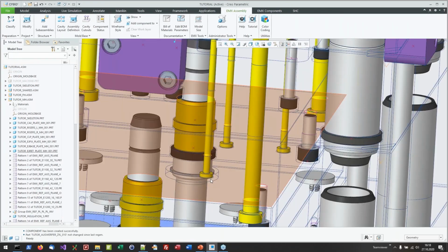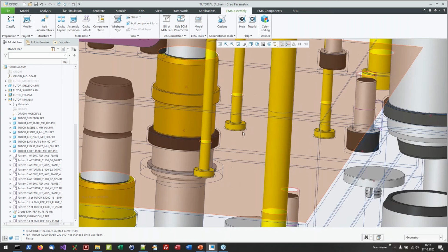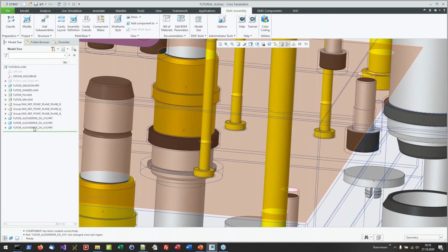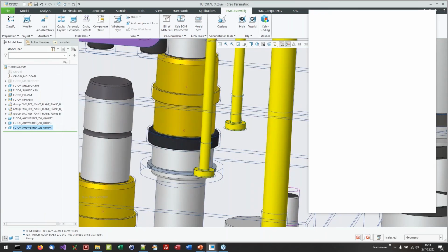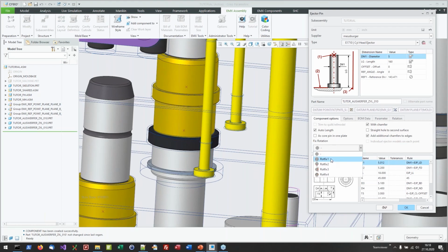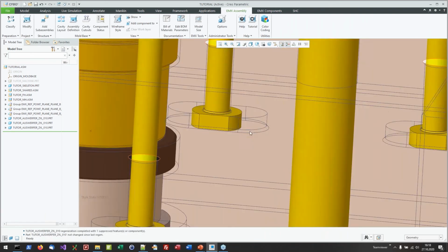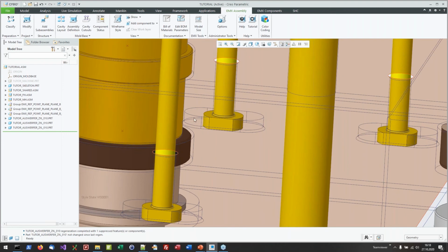The chamfers will not only be created in case it's a round cylindrical surface. Let me show you this: if I say modify and click on, for example, this rod fix, say okay, the cutouts will be recreated, and here we have a different shape, and the chamfer will also be created for this kind of edges.